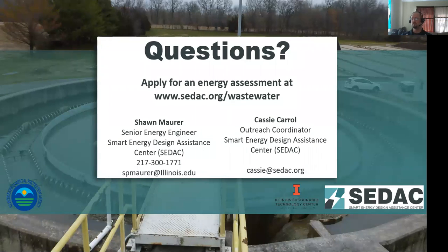So an engineer that's programming the SCADA system will enter in information about the installed horsepower of equipment, VFD installed on that, and then calculate both power and energy draw from those systems. I've also seen it done with direct metering of those, sub-metering of those systems. So an electric meter can be installed and report back to the SCADA system to build a benchmarking. And I would recommend that.